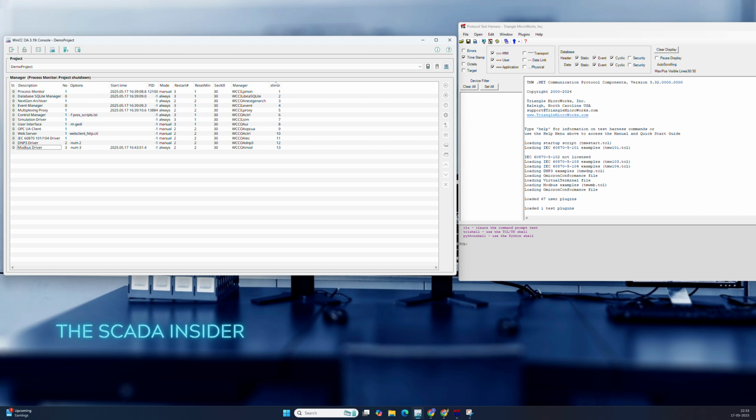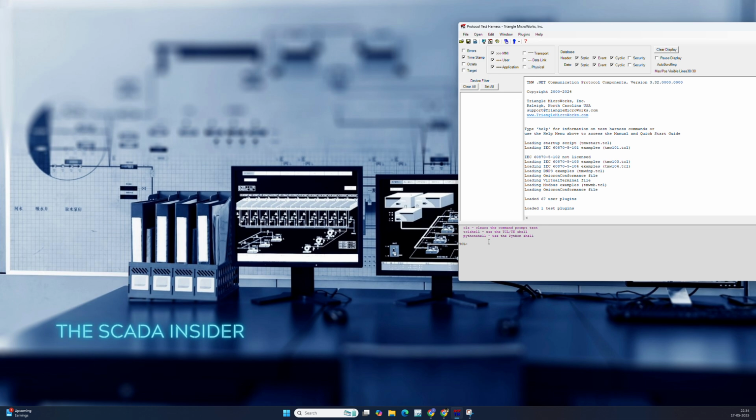Okay. Now the third part in Modbus is that we have different memory addresses for different kinds of register types and function codes. Like we have register types such as coil, discrete input registers, and holding registers, along with their function codes. Okay. Now we will do the configuration, so you will get a clear idea how we do this kind of communication for Modbus in the WinCC system.